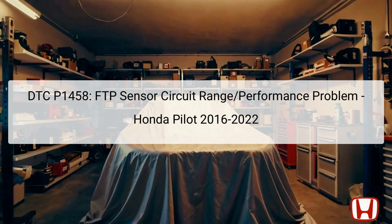It is primarily located near the evap canister, which is typically found on the underside of the vehicle, close to the fuel tank. This sensor provides vital data to the powertrain control module, or PCM, enabling it to adjust fuel mixture and emission levels accordingly. A malfunction or poor performance of the FTP sensor can lead to various issues, including increased emissions and decreased fuel efficiency. Understanding and diagnosing this DTC is essential for maintaining your Honda Pilot's performance and compliance with emissions regulations.